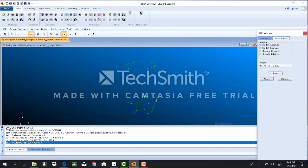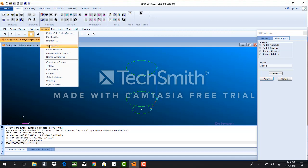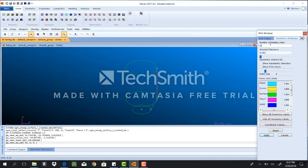Then we go to viewing and angles and enter 300 and then apply it. We'll go to display in geometry, going to the number of display lines 3 and a chordal tolerance of 0.001 and then apply it.